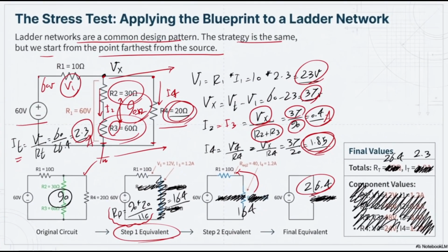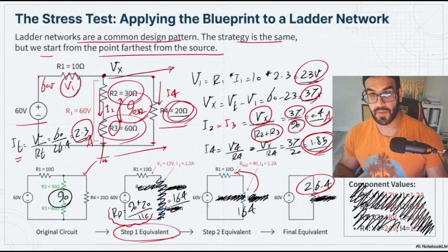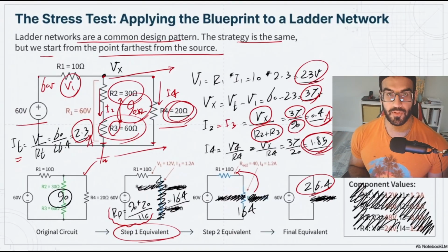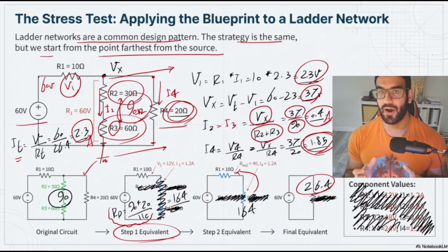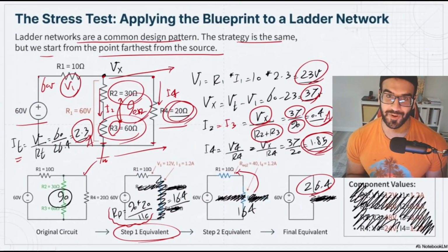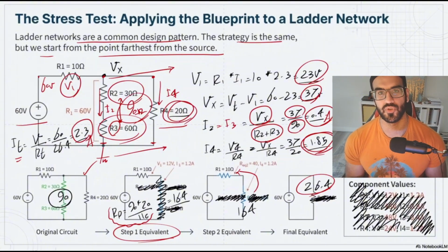So again, sorry about the things that happened. I just found it out, and I thought it would be better to record it for you to show that not all the time you have the right answer. You know what happened over here? At this point, I assumed that the resistances I have, 30 and 60, weren't in series, they were in parallel. That's why if you find the parallel of 60 and 30, you have 20, which leads you to a very good number, but still it's not going to be correct. So that's why you have to be careful. It doesn't matter how many years of experience you have or how many students you have taught. Sometimes you could also have the problem.